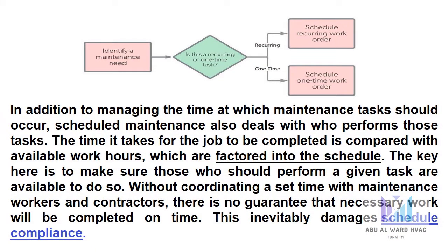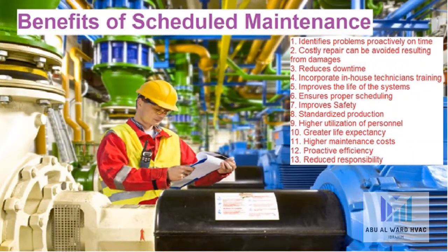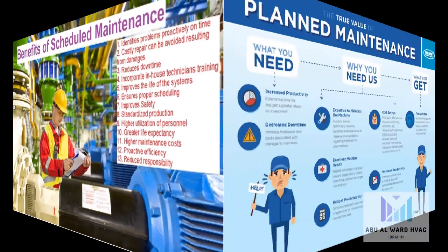Scheduled maintenance workflow. Scheduled maintenance often occurs at repeating intervals, such as changing an air filter every March and September, or conducting a performance inspection at the start of each year. Maintenance may also be scheduled to fulfill a work order. Once a problem is discovered, a maintenance scheduler works with a maintenance planner to resolve the problem. A time is then scheduled to conduct necessary repairs.